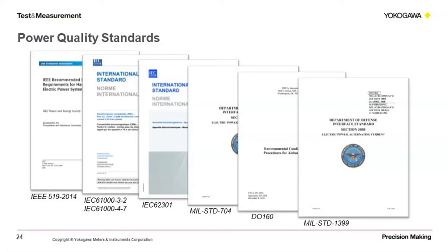IEC 61000-3-2 and IEC 61000-3-4 both define the limits for harmonic and current emissions, what we also call EMC. IEC 62301, what we call standby power. The objective is to provide a method to test and determine the power consumption of a range of appliances and equipment in standby mode. In the United States and North America, the Energy Star standard is typically used for testing these limits.